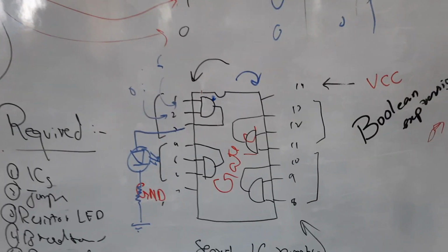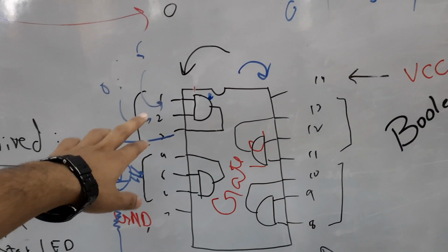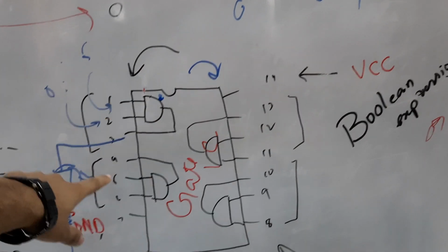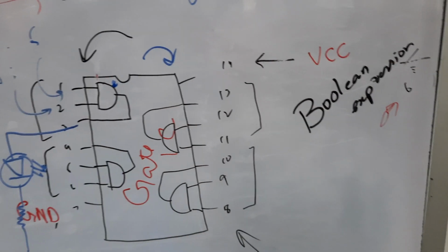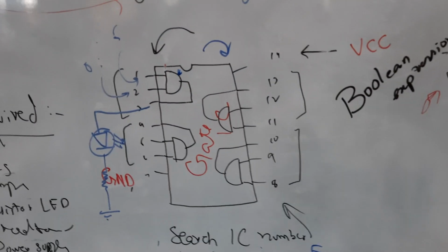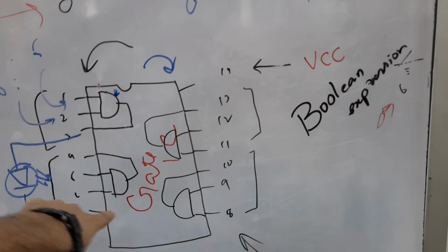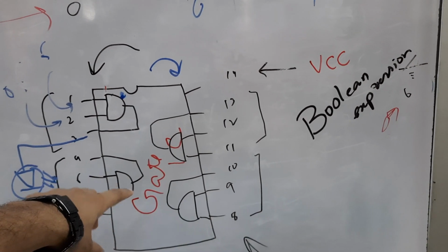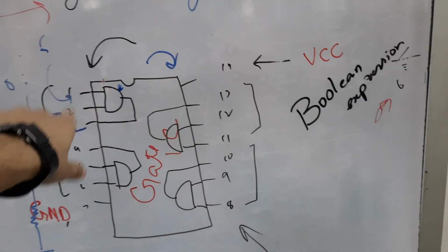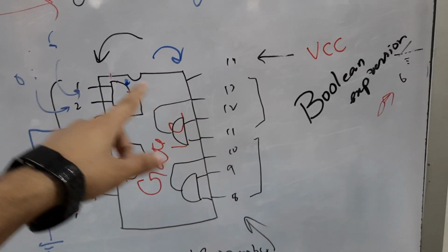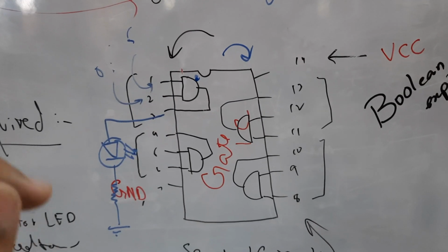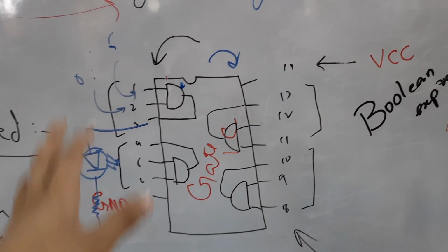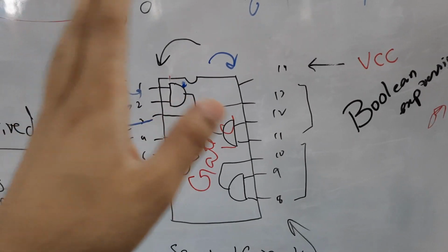If in case one gate is not working, you can use another gate from the other 3 pins. Similarly, from the right side you can also find 2 gates as well. The arrangement of gates inside is not permanent. You can check the exact pinout or exact configuration of the gates inside the IC through Google. For example, you are given an IC with the number 74LS04 or 74LS00.